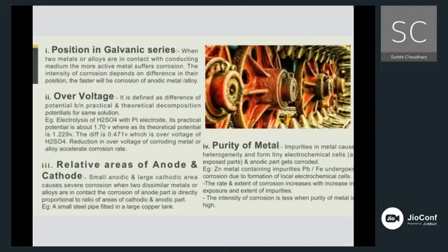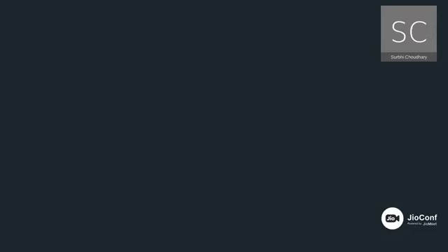If any metal piece is kept in the atmosphere, there is a reaction with the oxygen, and a thin layer covers the metal surface. The specific volume ratio is the term we use for the ratio of the volume of the metal oxide to the metal, because the exposure leads to the formation of metal oxide over the metal.